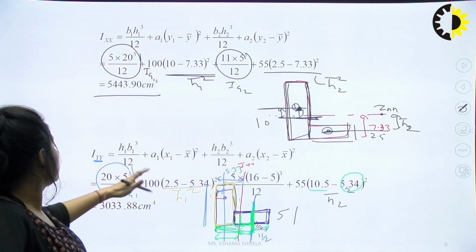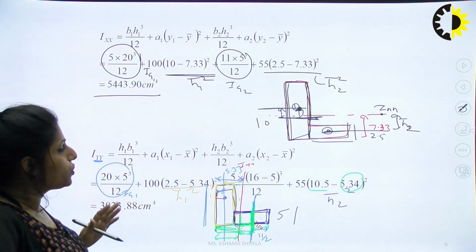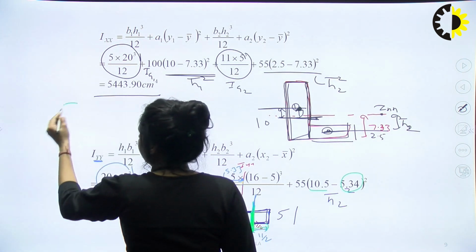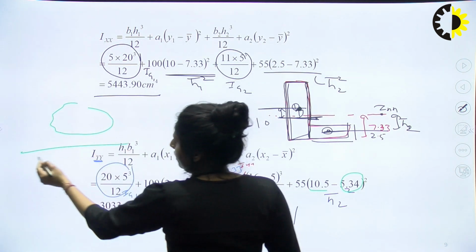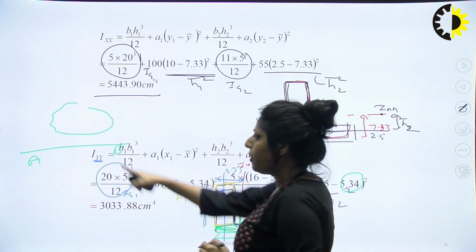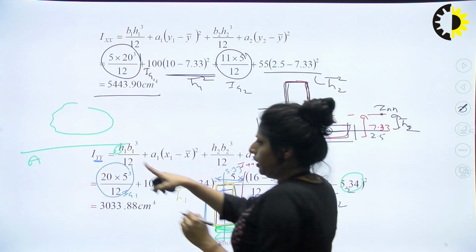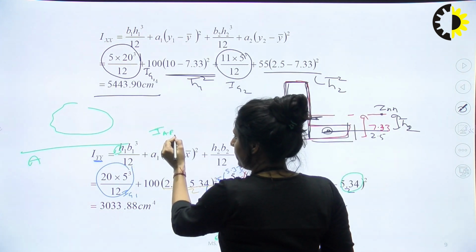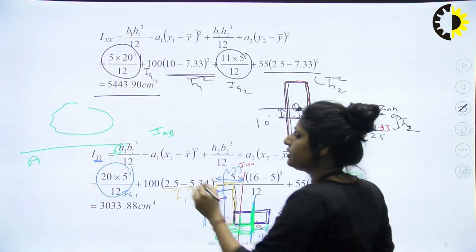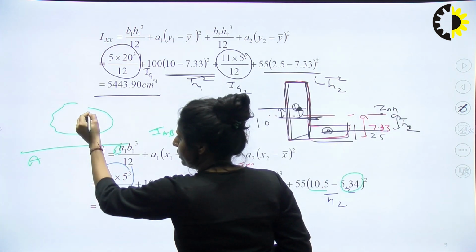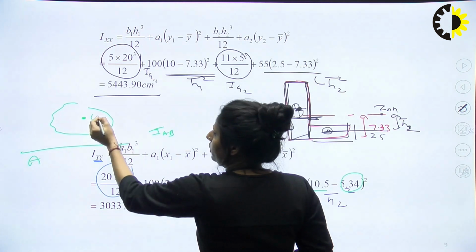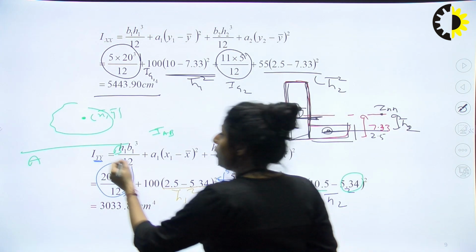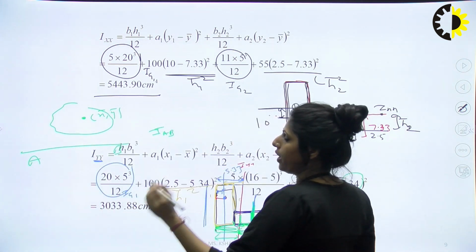So all the questions, solve it and find the answer. All the questions simply depend on the parallel axis theorem. We need to find the value about this AB. If I need to find the moment of inertia about AB, what we need to do is simply find the centroid of this diagram. If the value for this diagram is x bar, y bar,